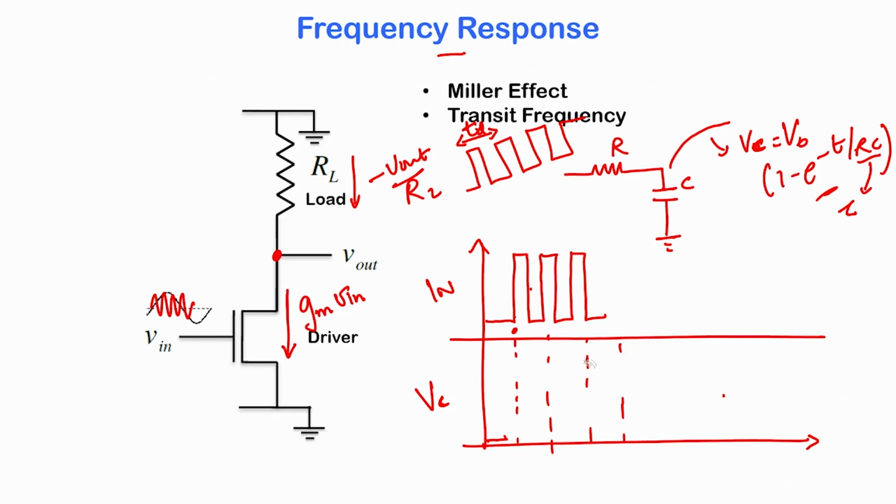So now you have a pulse that has got a higher frequency, you have increased the input frequency of the pulse. So now the capacitor tries to take its time, it has got a time constant of RC. RC has not changed, you have only changed the time period of this pulse. So it is going to try to climb, but you have not given it enough time to charge fully. So it is going to climb till here, and then it has started to discharge, and then it is going to climb till there and start to discharge. And therefore earlier the capacitor was climbing a lot more, it was getting charged a lot more, but now we are allowing it to charge only a little.